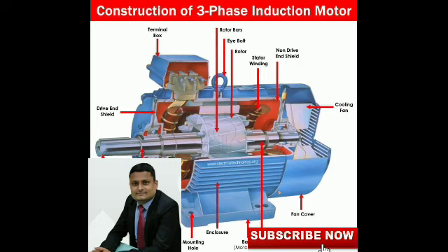Now another checkpoint, for length L. If the length of the armature stator is more than 10 to 12 cm, ducts must be provided to enhance the cooling. Each duct has a width of 8 to 10 mm.